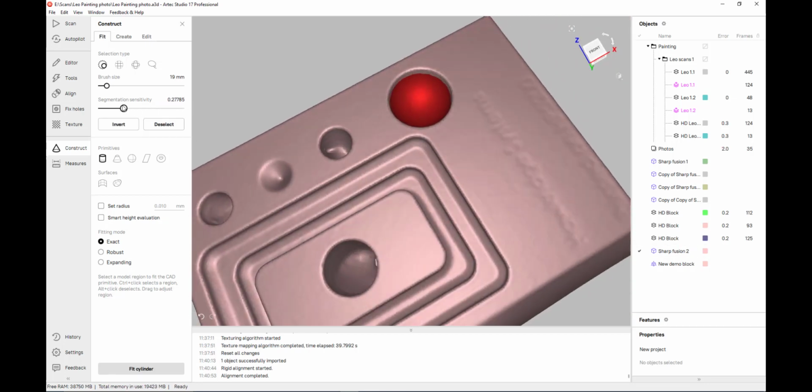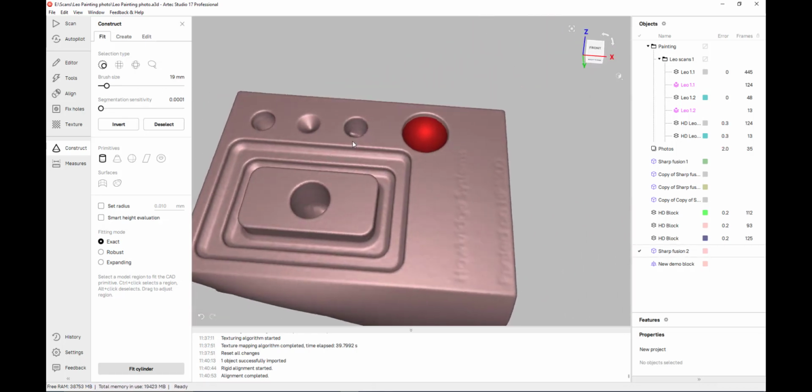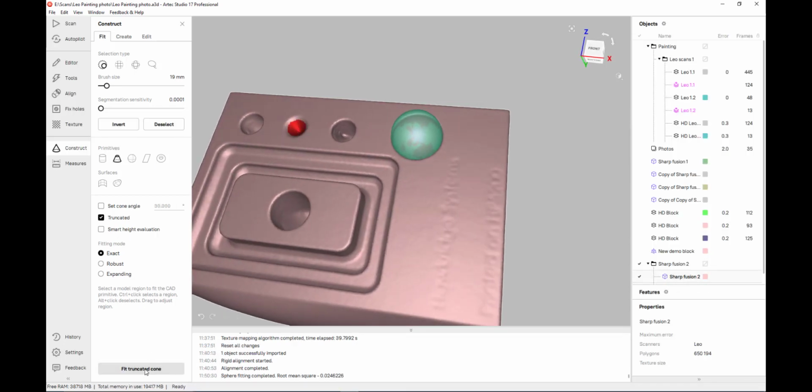With our data selected, we can choose the primitive CAD features we want to generate based off the average of our triangles that are highlighted red. The different selection methods can be useful to grab specific areas separated from one another, or if the flood selection doesn't properly choose. We can also remove some of our selected area by holding down the Alt key.